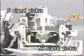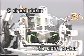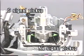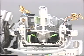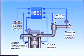In ESA, the distributor has two integrated pickup coils, one of which generates an engine speed, or NE signal, and the other of which a crank angle reference position, or G signal. While the engine is running, these signals are continually transmitted to the ECU. In case of the D-type EFI engine, other sensors are provided for the ECU, such as the vacuum sensor, throttle position sensor, knock sensor, water temperature sensor, and vehicle speed sensor.